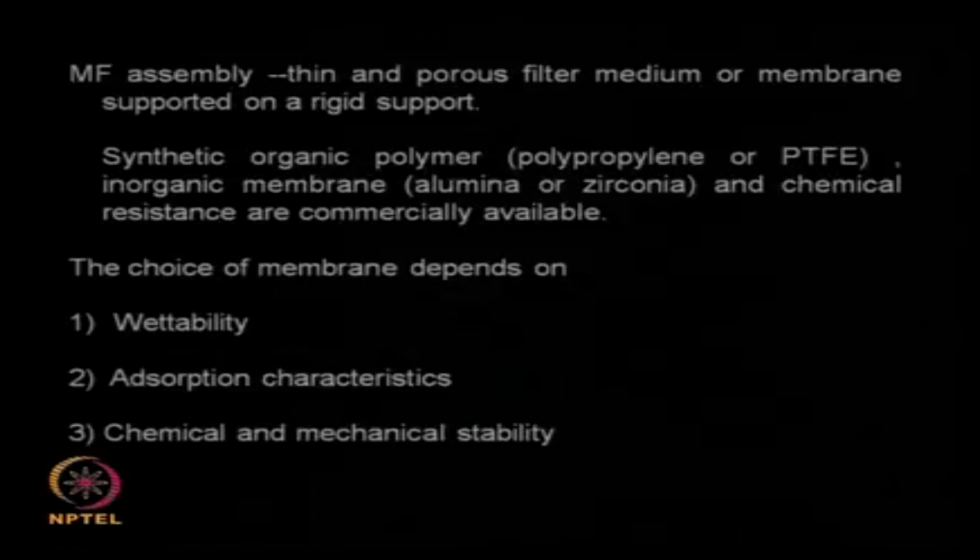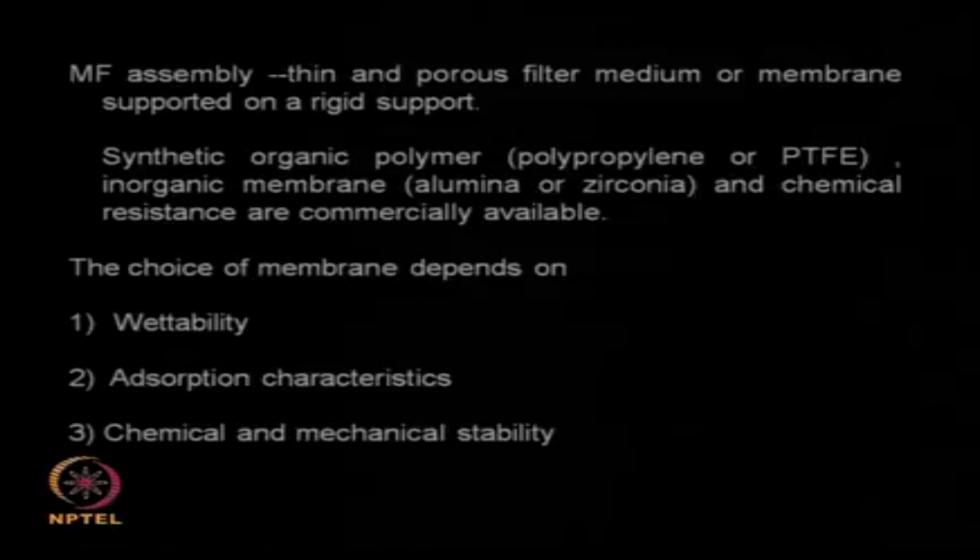Chemical and mechanical stability: it should be chemically inert, otherwise we do not want any reaction taking place between the solution and the membrane. It should be mechanically stable because we are applying pressure, and sometimes you may have solids causing attrition to the membrane surface.